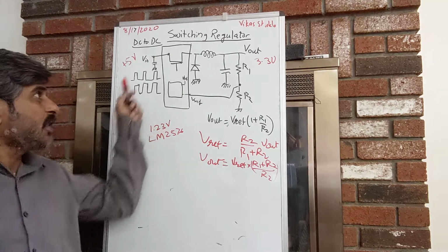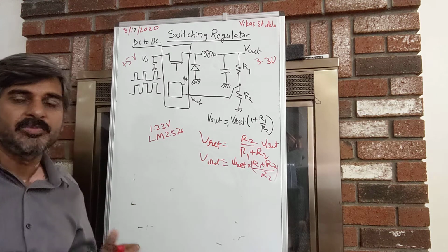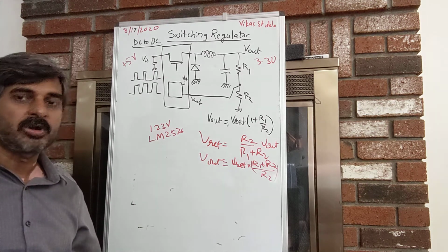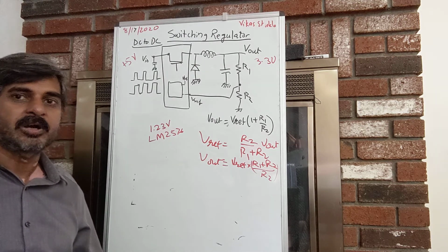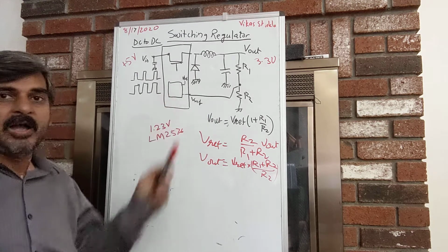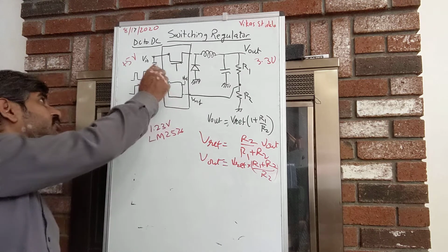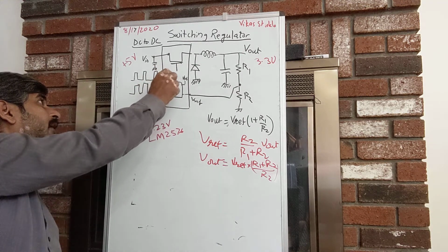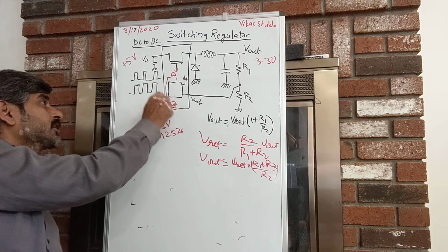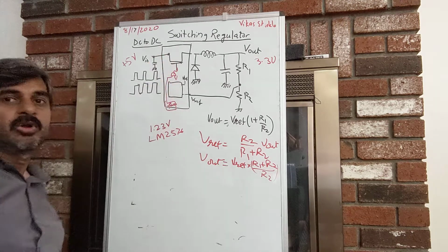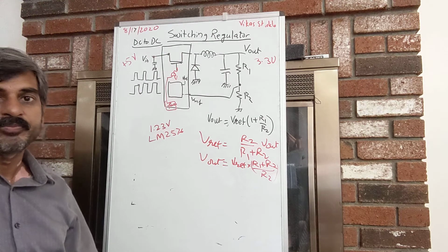So in theory, we could design it using discrete chips, but the reason they are inside an IC is that the chip does some more functions. One of the functions, for example, is the thermal cutoff. They have a kind of thermal sensor, a diode, and you can think of that diode as ANDing this thing. So if the thermal diode senses it is too hot, it will shut it down to 0 and resume it when the temperature comes back to normal.